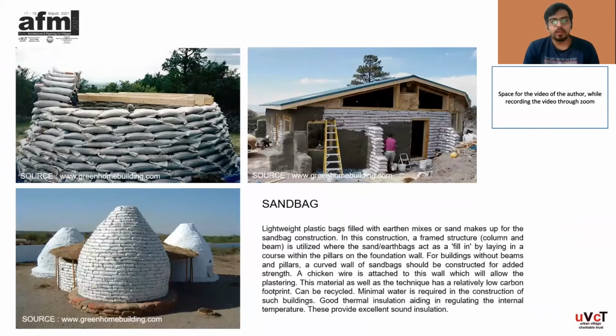Sandbag. Lightweight plastic bags filled with earthen mixes or sand make up sandbag construction. In this construction, a frame structure of columns and beams is utilized where the sandbag earth acts as a fill-in, laying a course within the pillars on the foundation wall. For buildings without beams and pillars, a curved wall of sandbags should be constructed for added strength. A chicken wire is then attached to the wall, which will allow the plastering.